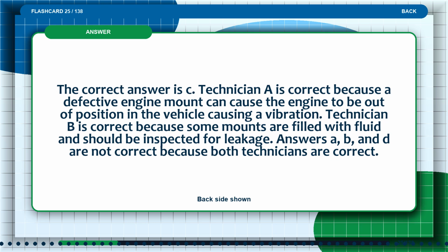The correct answer is C. Technician A is correct because a defective engine mount can cause the engine to be out of position in the vehicle, causing a vibration. Technician B is correct because some mounts are filled with fluid and should be inspected for leakage. Answers A, B, and D are not correct because both technicians are correct.